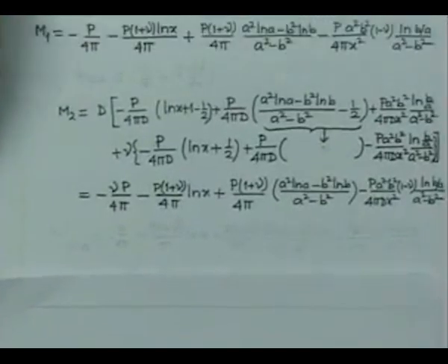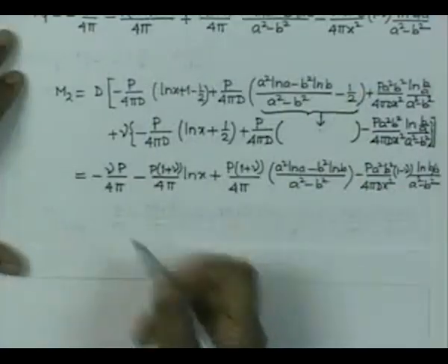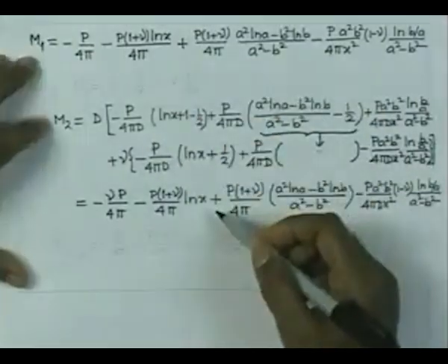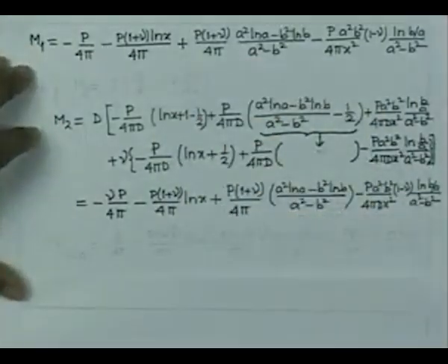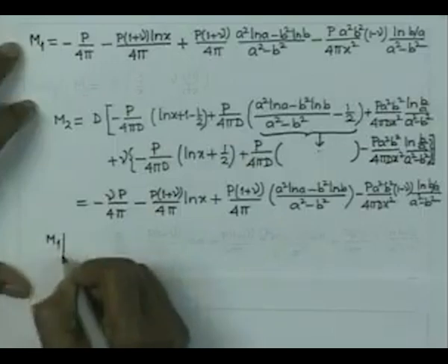So, finally, if you want to calculate the stresses at the location r equal to a, you can evaluate the bending moments. Substituting x is equal to a in the two expressions here, you get the bending moments which are critical. So, we will get now M1 at x is equal to a,